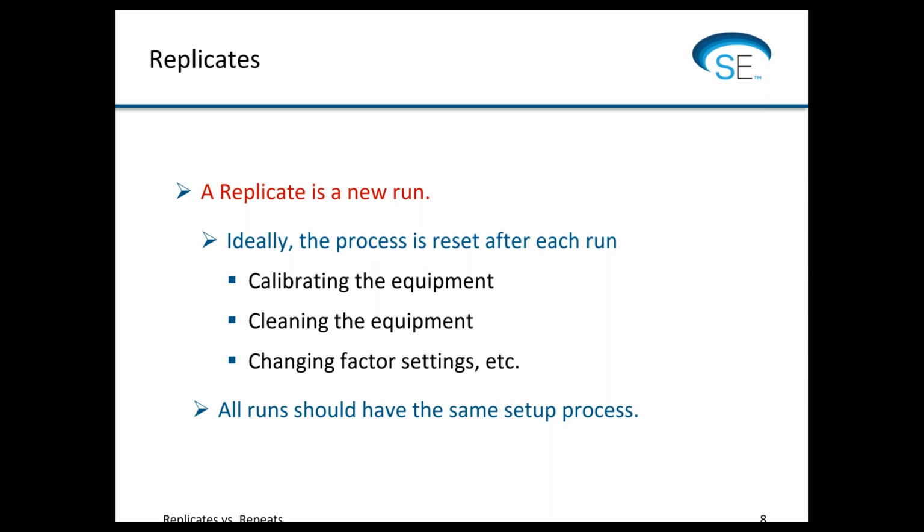So remember, when we say we're controlling factors in a DOE, so we're controlling temperature, we're really not controlling temperature directly, we're controlling the set point for temperature. And every time we change the controls to a different temperature, it varies around that set point.